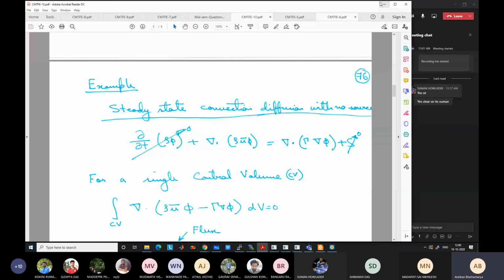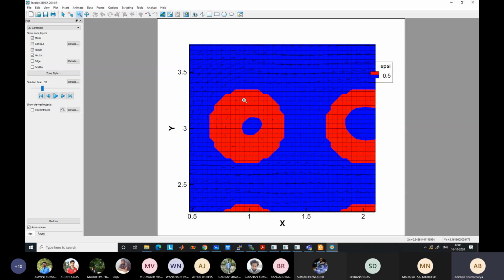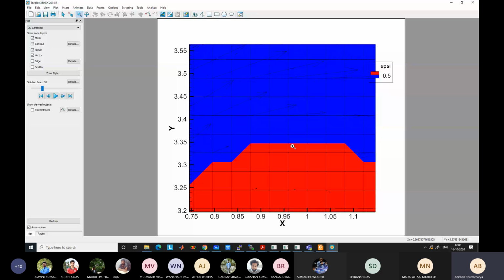So it is actually at the center point, but you don't have any other known value in the control volume, like I have shown in the example here. What I have shown in this example is that, say, this point here has a value of 1, this has 0.5, and this has 0, for example. So actually the liquid fraction is obviously not 0.5 at every location, right?